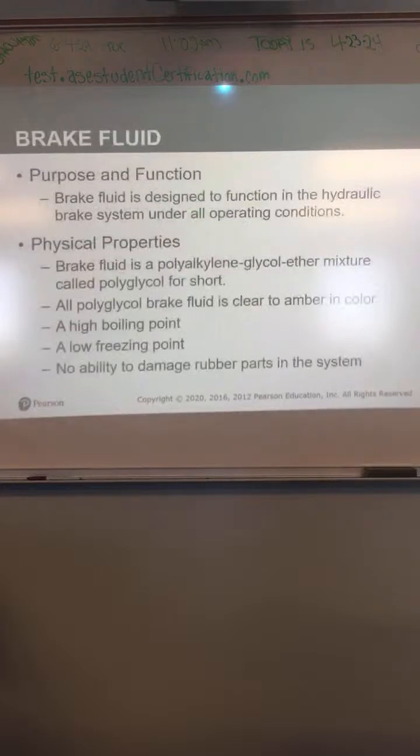Can you repeat that, please? Sometimes somebody puts what in the what? If you put the wrong brake fluid in the car, it contaminates the system. Because I've seen people put whatever, not even brake fluid. Somebody's not paying attention or whatever, maybe they'll put power steering fluid or something in the master cylinder. It contaminates the system, and you end up with dragging brakes and all kinds of problems, and then you have to replace all the components in there that have rubber in them.